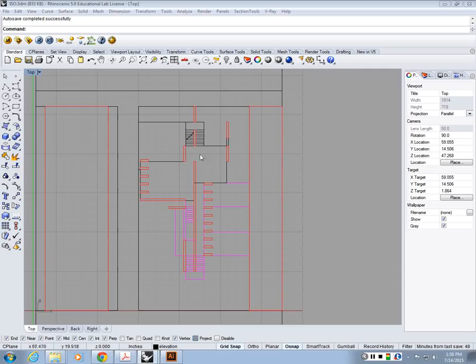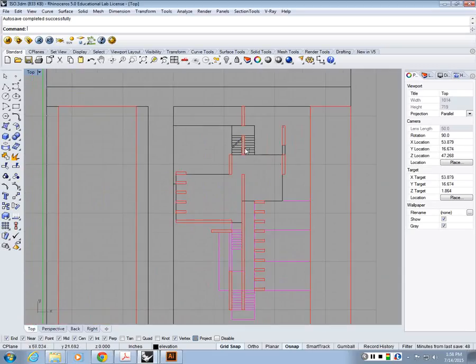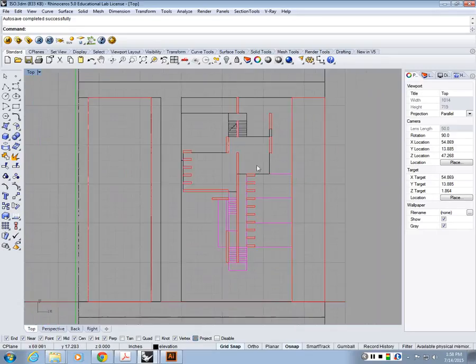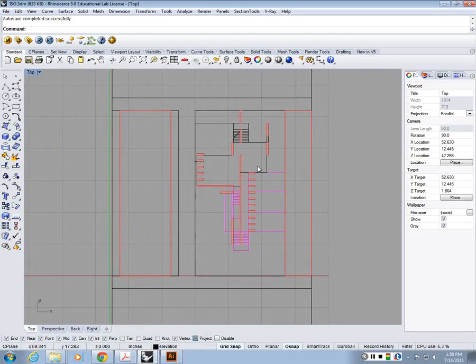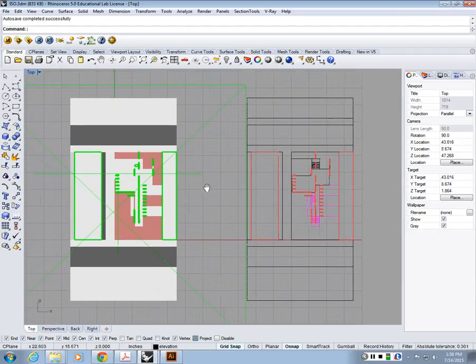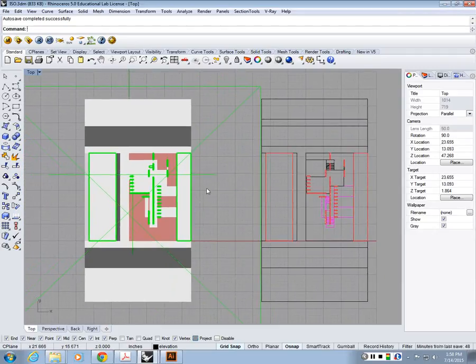I'm cutting through the red elements in plan, and the black lines are in elevation, as well as the magenta lines. The magenta lines are going to be lighter. But I also have some elements that I'm not seeing in this view, which are above my head, and they have to be dashed. One way to see them would be to flip the direction of your clipping plane and do a Make 2D in the opposite direction, and try to juxtapose it with your plan. So I'll show you how you can do that.